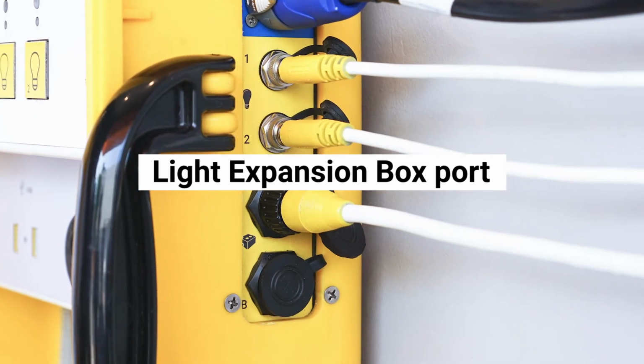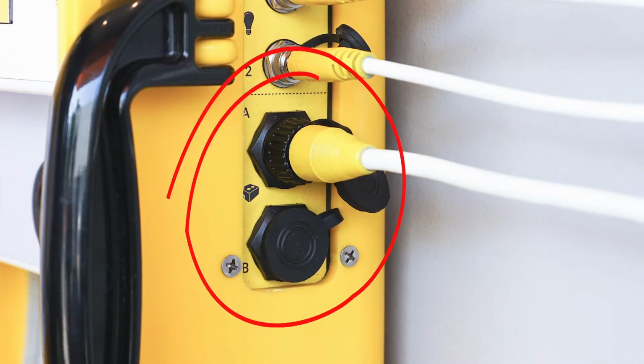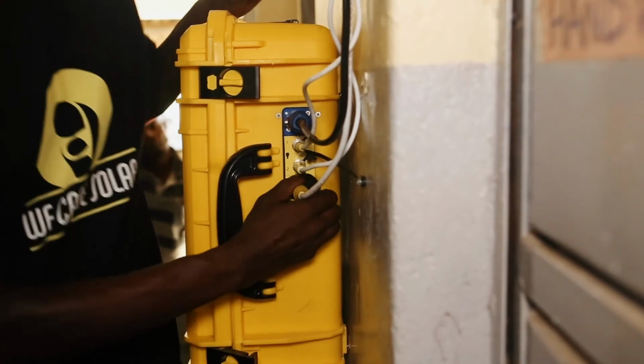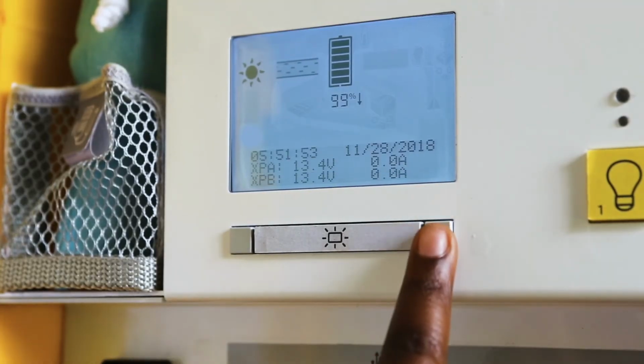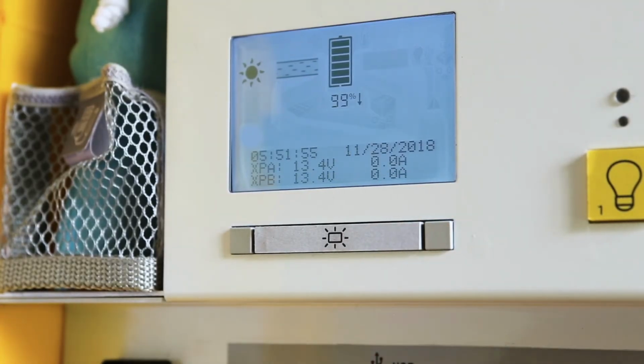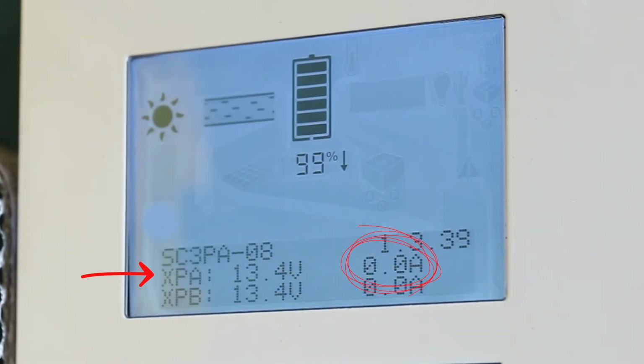Light expansion box port. At the side panel of the Solar Suitcase, there are 2 expansion ports, A and B. This is where you plug in the light expansion box. This screen shows the voltage available for the ports and how much current is flowing to the attached expansion box. In this example, XPA, expansion port A, has no power available.